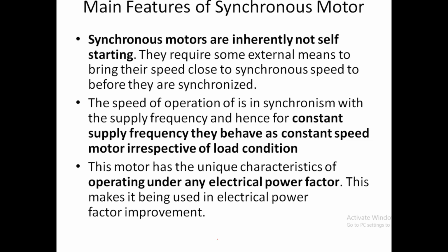So these are again the main features of the synchronous motor. Synchronous motors are inherently not self-starting; we are giving some external means for starting. But when it is started, it always rotates with a constant speed and constant frequency, irrespective of the load condition. In induction motors there may be some changes with the load, but here there is no change. It is always rotating at synchronous speed.